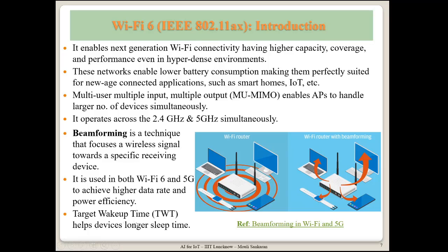Another important thing which is specific to IoT is target wake time. See, what happens is, I will tell you, you have a transmitter. Let me assume that it is a Wi-Fi router and there is an IoT device. Now they normally send a beacon, saying that I am there, and this is the distance and this is the frequency I'm transmitting, so that the IoT device can communicate back. Sometimes the devices may say that this is the time you are supposed to transmit, so that the IoT device can send it back during that particular time.